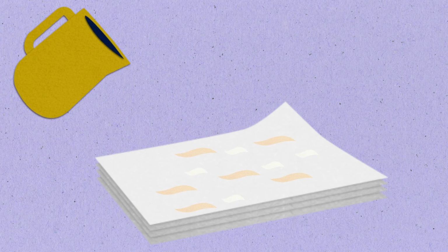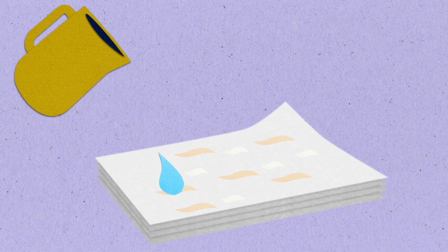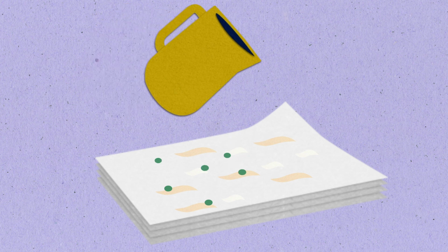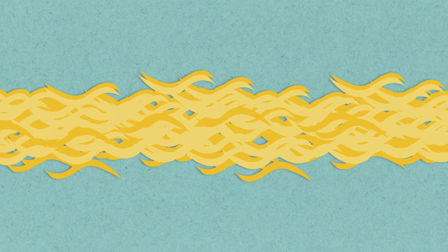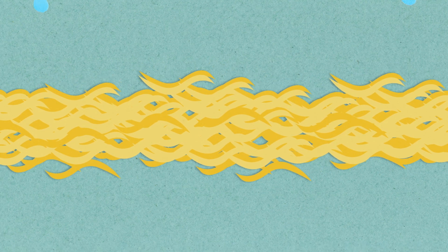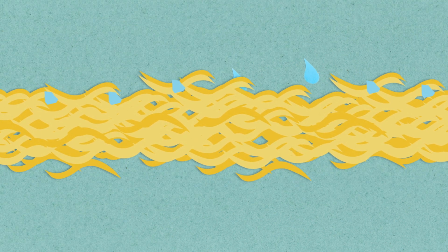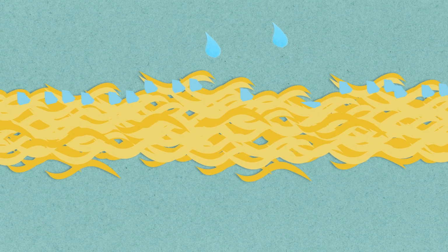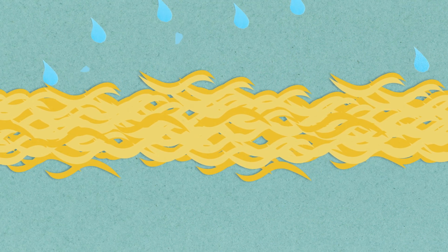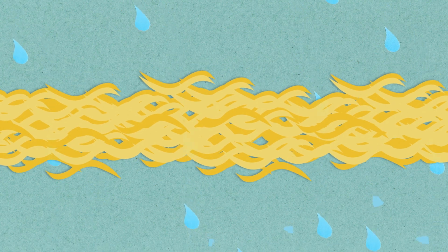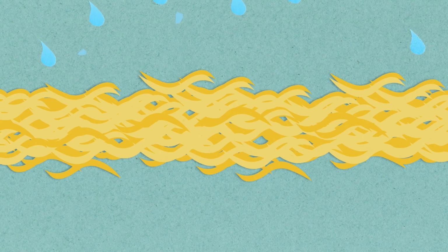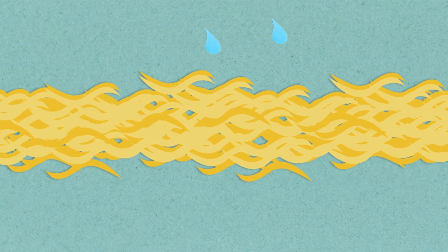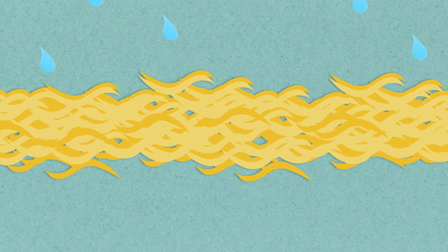Retention additives are process additives used to retain small particles and paper chemicals in the sheet, rather than draining through the wire. Depending on paper grade, it is important to have the correct level of retention. Too much retention causes high flocculation and fibers sticking to forming fabrics. Not enough retention lets small particles and chemicals drain through the sheet and accumulate in the whitewater system. This causes several issues, such as deposits, poor runnability, increased usage of functional chemicals, and sheet two-sidedness.